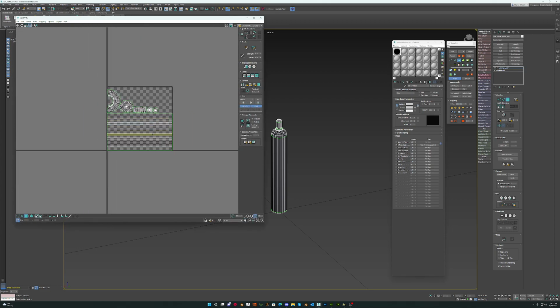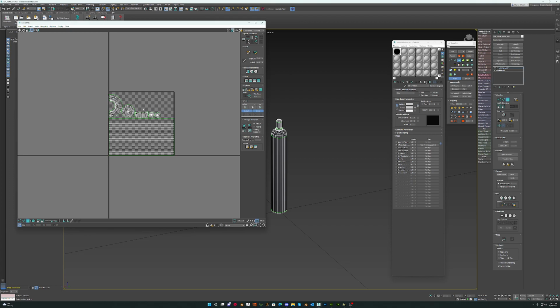So a note on the UVs. Channel 1 essentially is from 0 to 1. It can't go outside of those bounds, simply because Substance Painter doesn't like it. Any transitions or parts of the mesh that are bridging between channels is not allowed. Channel 2 can be scaled, can be any size you want and any place you want. Channel 3 can be scaled again to any size you want. Channel 4 must be from the 0 to 1 space again.